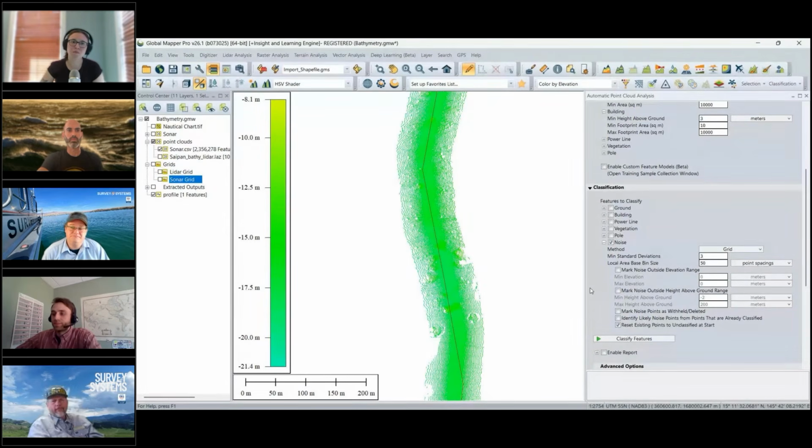Awesome. And from the data collection side, can that data be noisy? Absolutely. It depends on which sensor you're using. We have several different sensors here at Survey Systems that we use. Bottom tracking is important, but you can't bottom track if you're interested in snippets and backscatter.